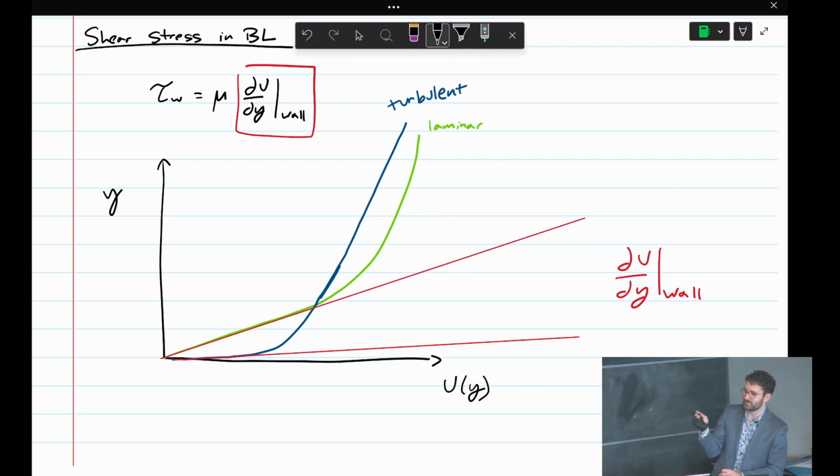And in turbulent flows, the only way our body interacts with the flow, all that happens instantaneously at the wall. So you need to get the wall right to get the rest of the flow right. But getting the wall right is very, very expensive. So that's one of, if not the main problem in simulating turbulent flows.